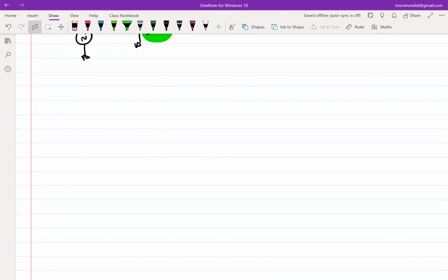Essentially, as I started this lecture, I said that we want to make an amplifier, or a voltage controlled voltage source, where V0 is K times Vi, where K is greater than 1. We want to make this using negative feedback, because we saw right at the beginning of the course that if we just use our transistors to get some Gm times R kind of gain, where Gm times R is greater than 1, the problem is that it is dependent on temperature, ambient variation, and so on. Which essentially means that this K needs to be accurate.